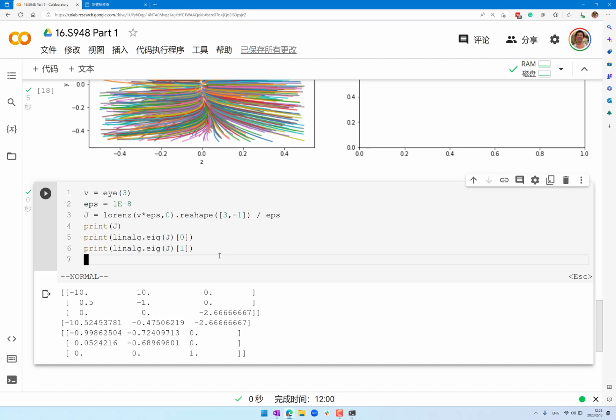But for systems that we are usually interested in for physical reasons, like turbulent flows, it is simply impossible to construct an identity matrix that is of the same dimension as the system itself. Just to give some simple examples, for most computational fluid dynamics simulations of turbulence, the dimension of the system is at least several million and can easily go to several billion or tens of billions.